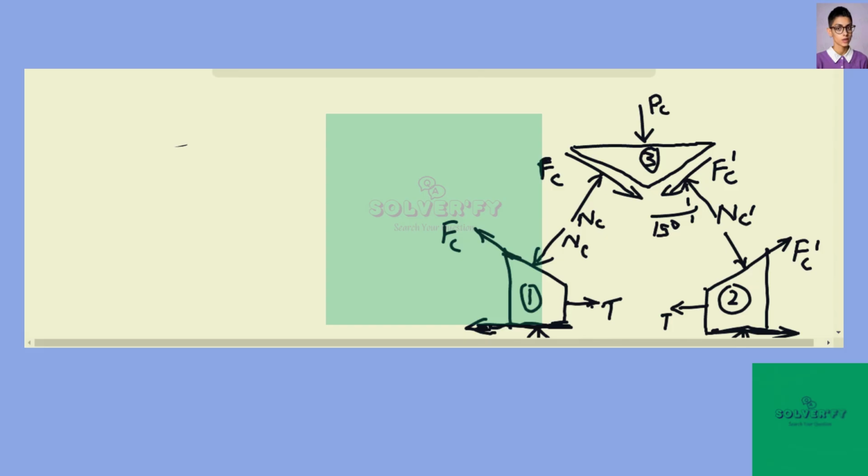Now, for the system shown here, we are considering screwing through two wedges. So we are going to apply, and we are tightening. So we have this equation: M is equal to W times the mean radius of the screw, r, times the tangent of the lead angle plus the angle of static friction, where W is the clamping force.